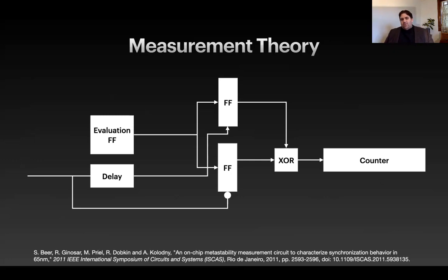That is what's being evaluated, and you can see that the output of that flip-flop is being fed into two more flip-flops. You will notice, though, that the two flip-flops in the middle of the page are not being fed by the same clock. The top one's clock is going to be fed by a delayed circuit, and we're going to see why on the next slide. The one on the bottom is actually going to trigger on the falling edge of the normal non-delayed clock.